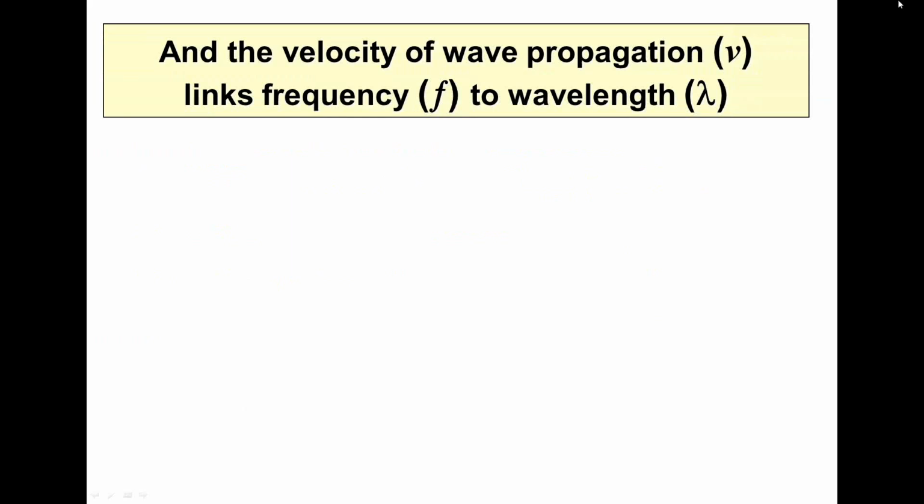So why are we interested in velocity? Well, I mentioned before, because we want to know the wavelength. V equals f lambda: the velocity equals the frequency times the wavelength. Generally speaking in EMC, we're measuring frequency. All our specifications are in frequency. Well, the continuous RF ones are anyway. And we want to know the wavelength in order to decide whether a trace needs to be treated like a transmission line or whatever, and they're tied together by the velocity.